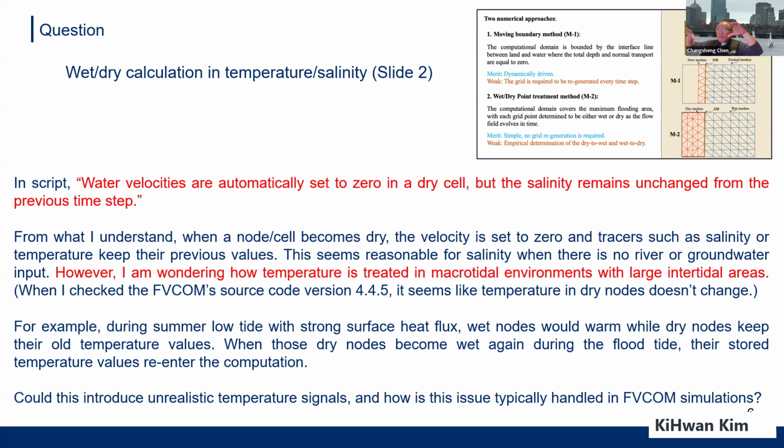So we used the data to develop a 1D model to determine what kind of erosion stress there is at the bottom, because that's very critical for sediment vertical movement, like suspension and deposition, which are really related to the erosion stress. So we used the satellite data and the 1D model to determine each region's stress. Then we put it in the model, and we found the model came out with a really good match with the observation. Something you can do similar, okay?